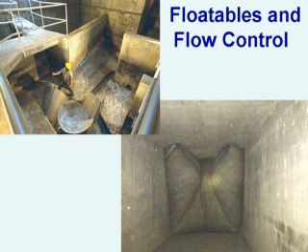And then after those vessels are full, the high-quality side treatment starts to take place, and that includes, of course, the screening up front, the vortex separation, the compressed media filter, and then UV disinfection. That flow, we found through testing of this facility for 5 years, that part of the facility will take about 15 MGD. The total plant is permitted for 48 MGD. And then after the high-rate treatment system occurs, the other vortexes open back up, and chemical disinfection occurs to treat the total waste stream. So there are actually two discharge points going into that outfall pipe. One is the UV disinfected effluent, and one is the chemical disinfected effluent. Both of them typically have fecal coliform levels of less than 100 fecal coliform counts per 100 ml.